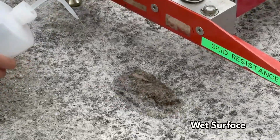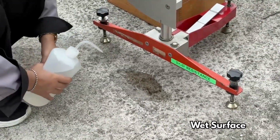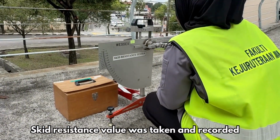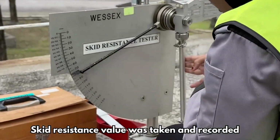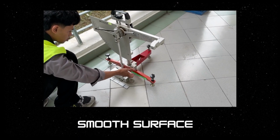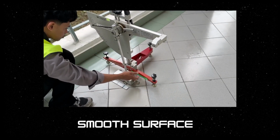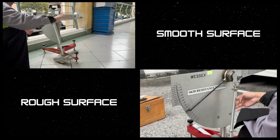The experiment was repeated for wet surface. A minimum of 3 skid resistance values was taken and recorded. The steps were repeated for smooth and rough surfaces. Data was taken and the average value was calculated and recorded.